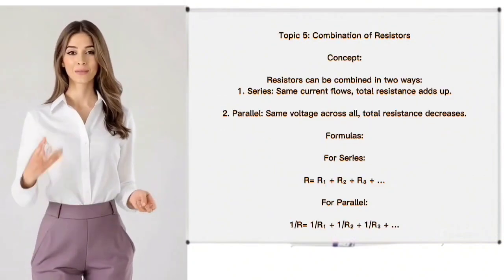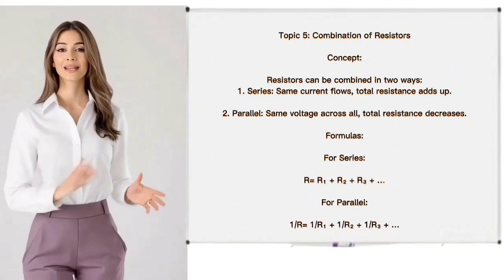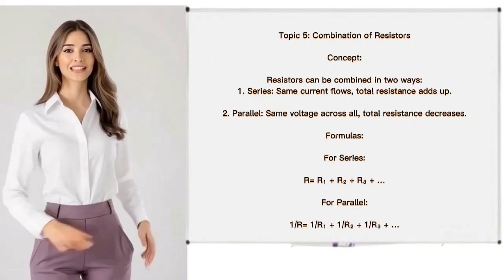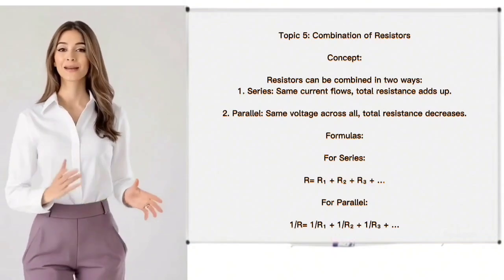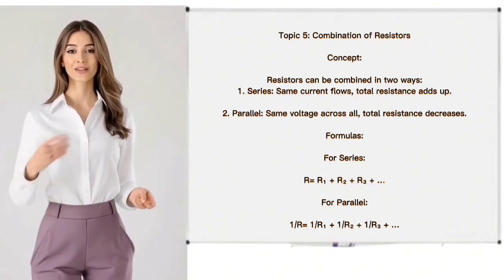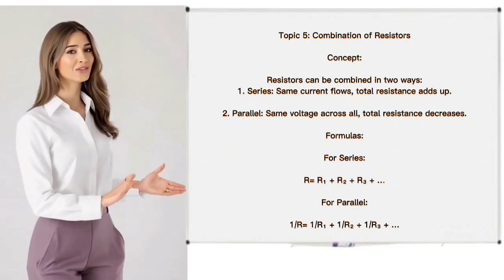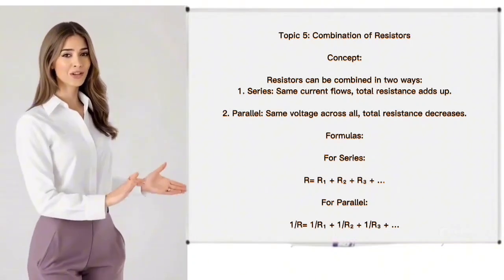Topic 5. Combination of resistors. Concept. Resistors can be combined in two ways. 1. Series: same current flows, total resistance adds up. 2. Parallel: same voltage across all, total resistance decreases. Formulas: for series, R = R1 + R2 + R3 + ... For parallel, 1/R = 1/R1 + 1/R2 + 1/R3 + ...